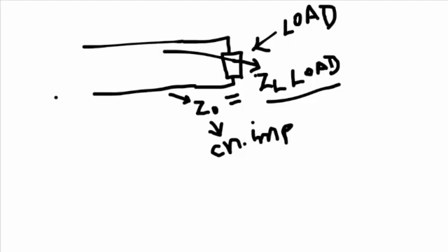This is the concept of microwave engineering, but this concept you can also see in electrical engineering, where you see a theorem called maximum power transfer theorem. There you see the Thevenin equivalent of this load should be equal to this load resistance should be equal to the Thevenin resistance of this circuit. So this is the basic idea behind this.